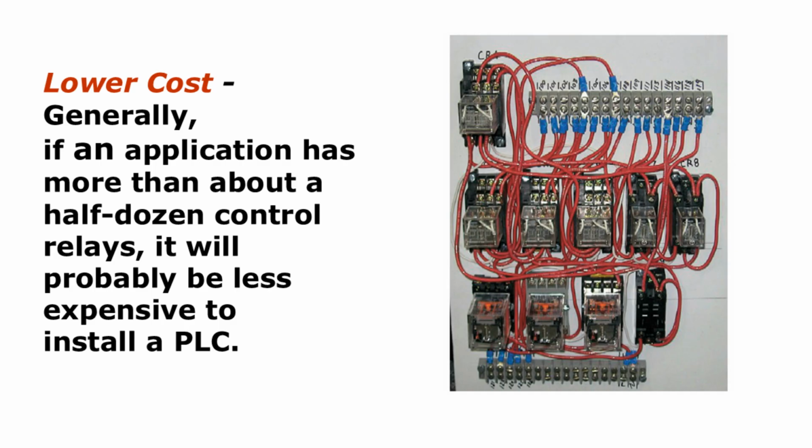Maintenance costs are also lower with PLCs. No worn-out relay contacts, fewer wiring faults, and easier troubleshooting. Changing the system doesn't require new relays or rewiring, just updating the program.